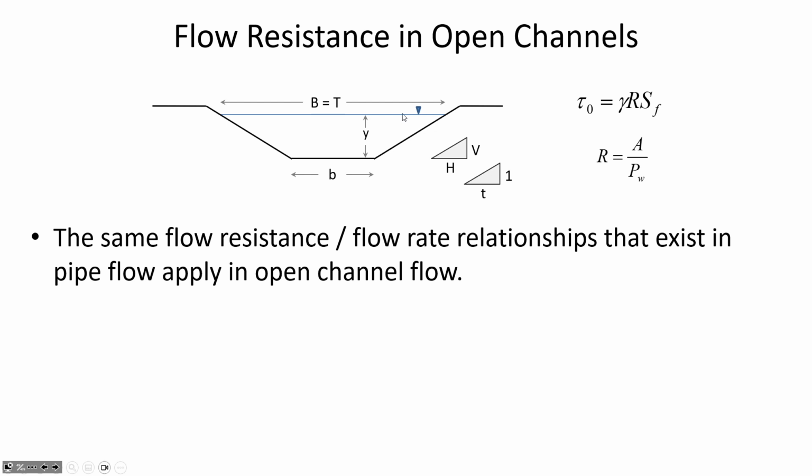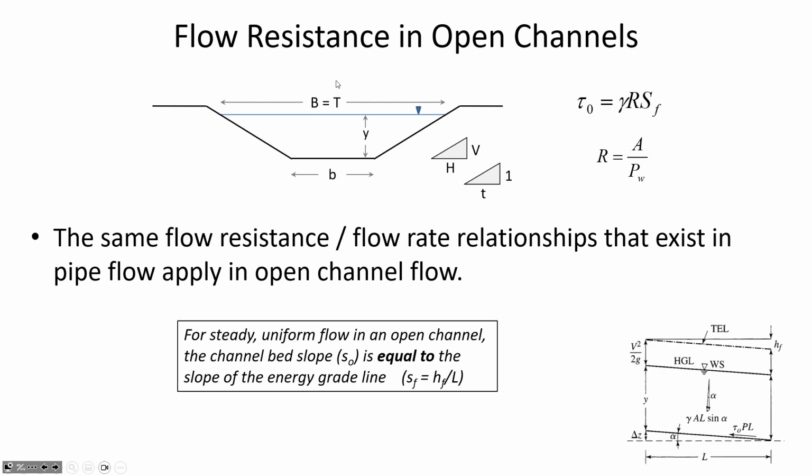And then the other thing is the wetted perimeter does not include the top because the water is in contact with air. So wetted perimeter is where does water touch the channel, or where does water touch something that isn't moving. So in this case, if this was a concrete lined trapezoidal channel, water would be touching this side segment and the bottom and the other side segment, but there isn't resistance being applied to the fluid by the air at the top. Maybe a little bit of resistance, but nothing like what it's encountering in the channel itself.